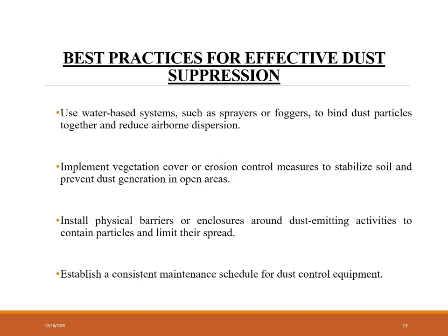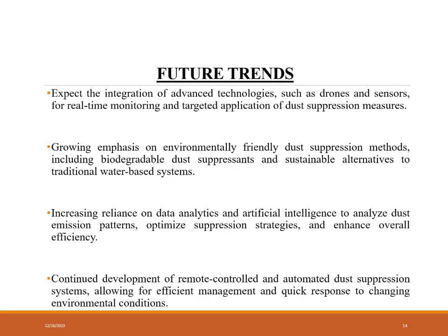Third, install physical barriers or enclosures around dust emitting activities to contain particles and limit their spread. Fourth, establish a consistent maintenance schedule for dust control equipment.